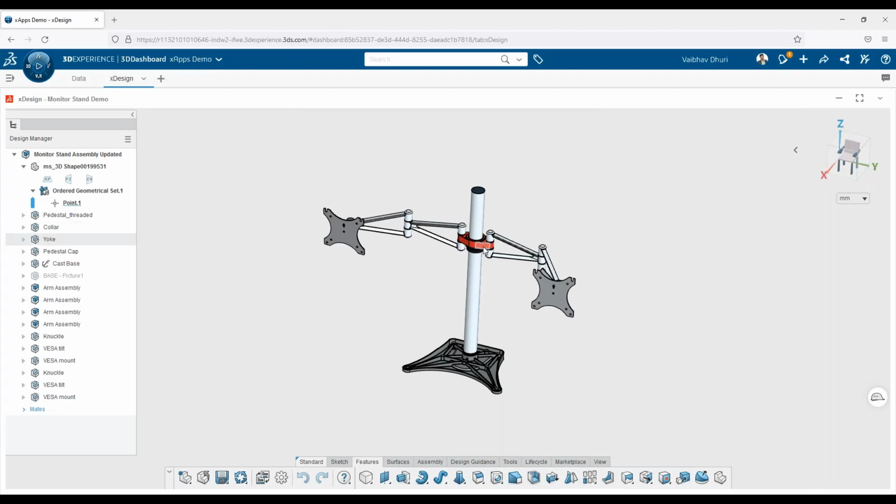Okay, so here we already have a previous yoke. If you want to replace it, all I need to do is just go to the replace command in the assembly. Now let me also talk about the modeling interface. So here you have a single modeling interface. You don't need to work separately on parts, with a separate interface for assemblies, maintaining different types of templates for that. You have a single modeling interface.